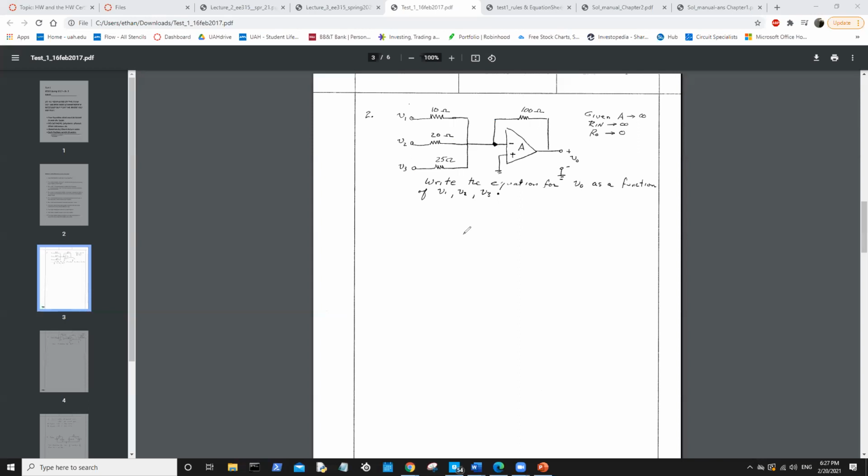Yep, basically. I think, probably for all the problems, but definitely this one, the biggest thing to take from this class is the assumptions: know that the voltage at that node is 0, there's a virtual ground, and know that nothing flows into the amplifier. And then everything else is basically just Kirchhoff's law. So you do it once at the output and then once where those 3 separate voltages come together.